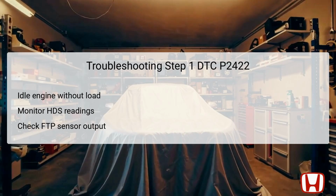If these values are outside of this range, then the PCM is detecting an anomaly which can warrant further inspection of various components in the EVAP system, including the FTP sensor. This initial step is crucial to establishing a baseline for diagnosing the source of the problem.